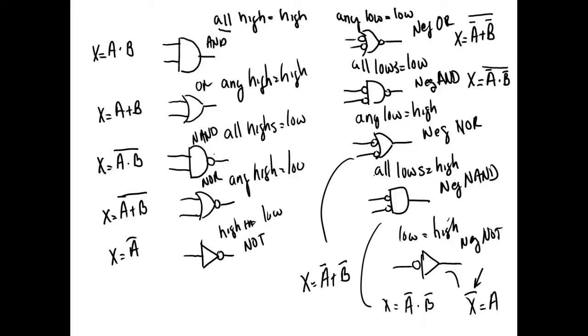If I've got 4 of these inside a single chip, and I need another circuit, then I'll do the combinations, and I only need one of these. That's going to leave me 3 more that I can do something with. So I'm not going to put a decoder chip in there if I can use those 3 to do the decoder that I need to do.